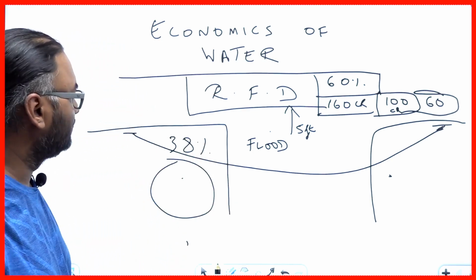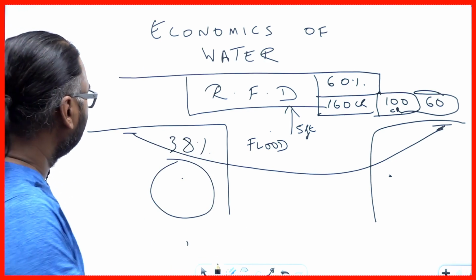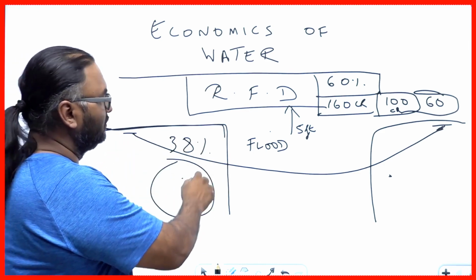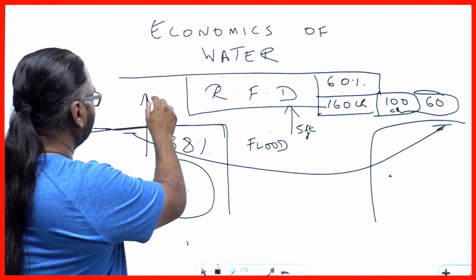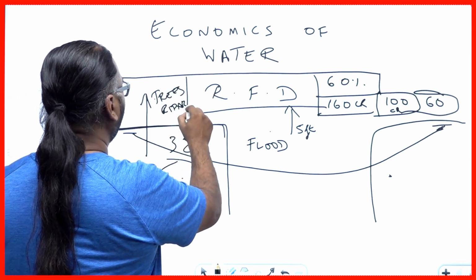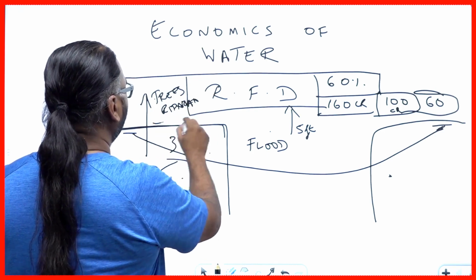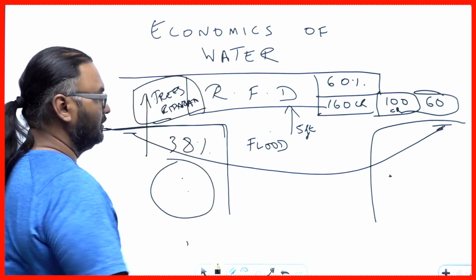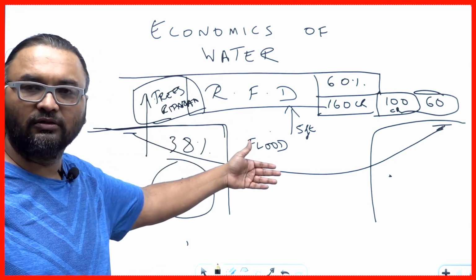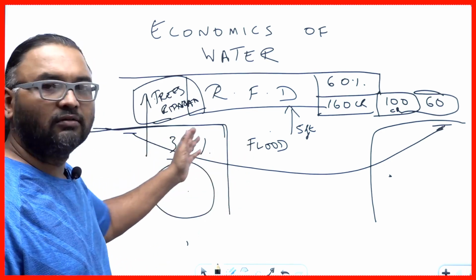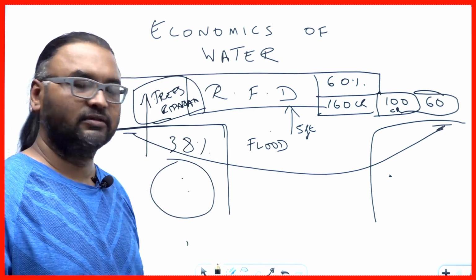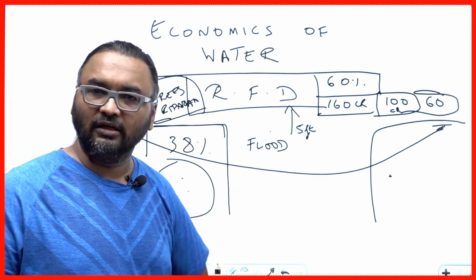Besides that, what is a bigger problem is that once you occupy this bank, it is very difficult to restore the natural habitat over here. The trees, the riparian forests, etc. will all get cut down. Now, when you cut down the natural habitat over here and you block the springs going into the river, whatever natural sources of water are there going into the river, you kill the river's ability to rejuvenate itself. In such a circumstance, the river is perhaps never able to come back to life.